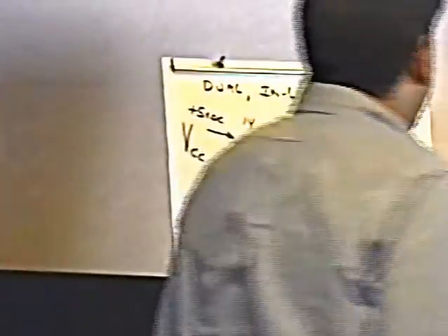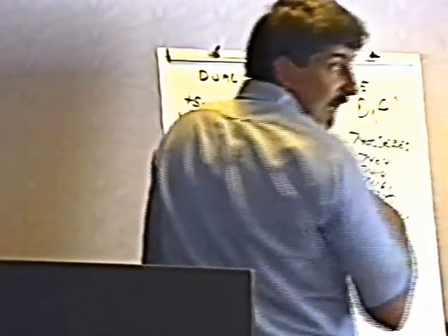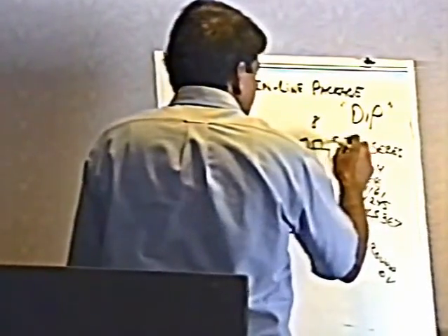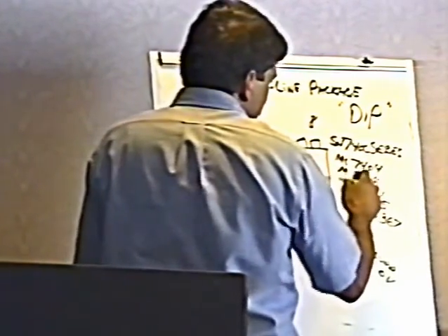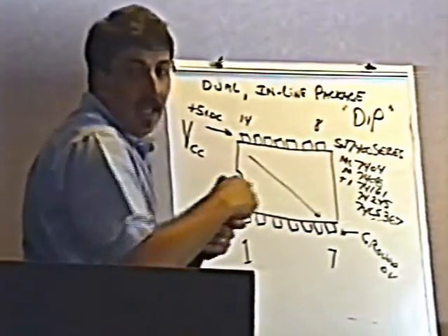Here's one that says M74LS374. Mitsubishi, exactly. You can see the Mitsubishi logo. You'll see this a lot. Many times you will see a one or two-letter prefix on the beginning of these things. It may say SN, it may say MC, it may say M, TI, something like that.